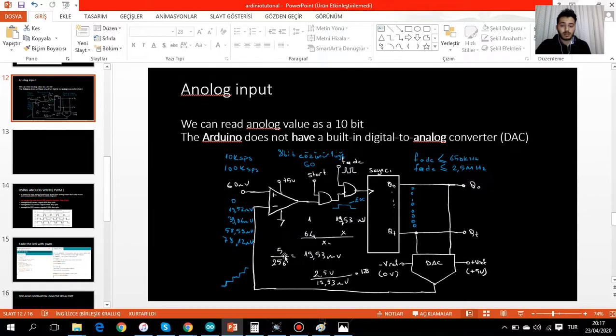At the same time, when you are counting up, it also converts that digital to an analog signal. In the 5th step I have got 78 millivolts. This means it is bigger than 60. It means my digital number here is 00100, it goes like that. It means 60 millivolts is represented with that specific number, but this is digital. You can also convert it into decimal. In brief, that is how analog input works, guys.